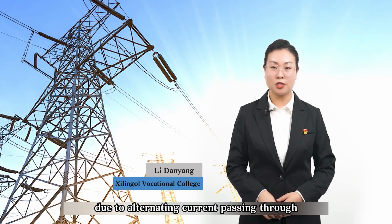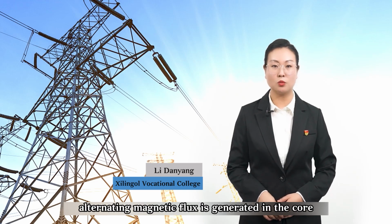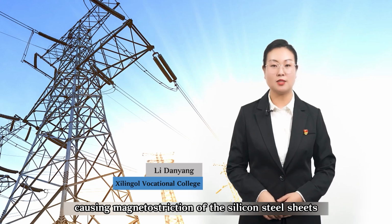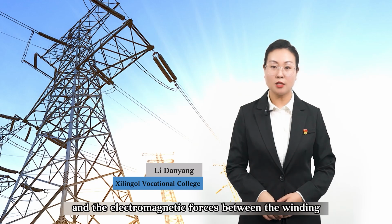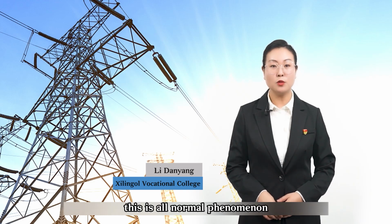Due to alternating current passing through the transformer windings, periodic alternating magnetic flux is generated in the core, causing magnetostriction of the silicon steel sheets. The magnetic forces between the core joints and laminations and the electromagnetic forces between the winding conductors cause vibrations, producing a continuous, uniform buzzing sound. This is all normal phenomenon.